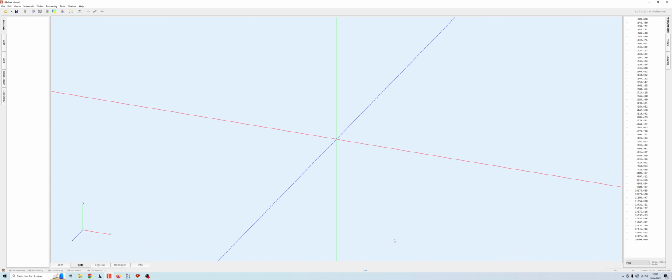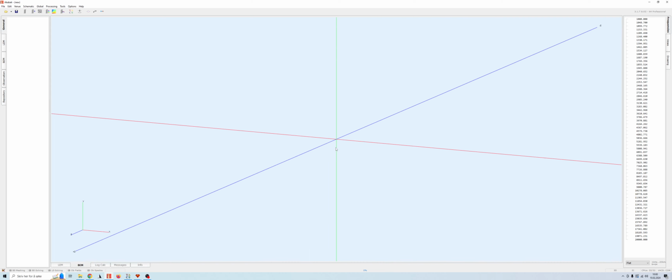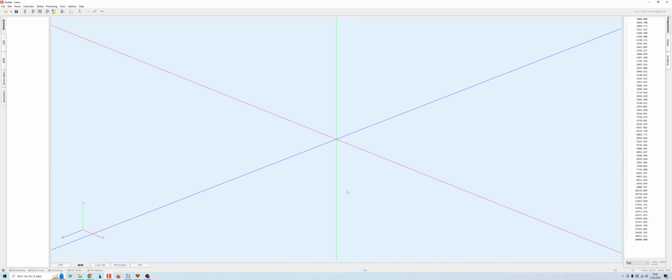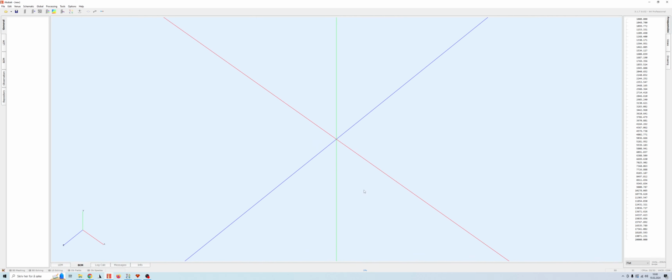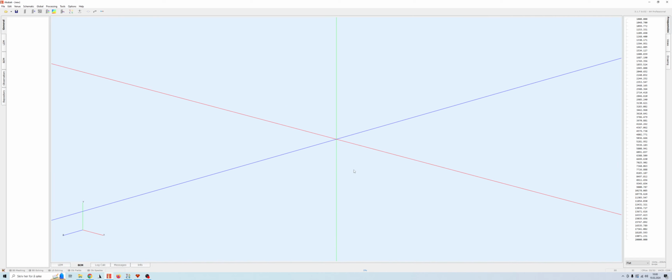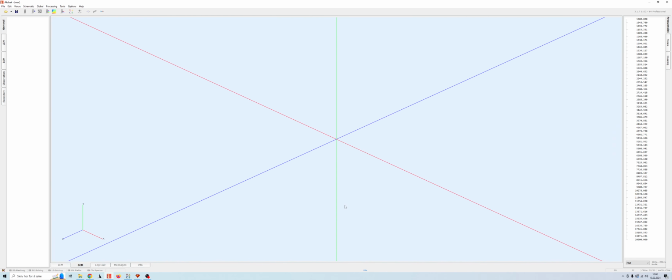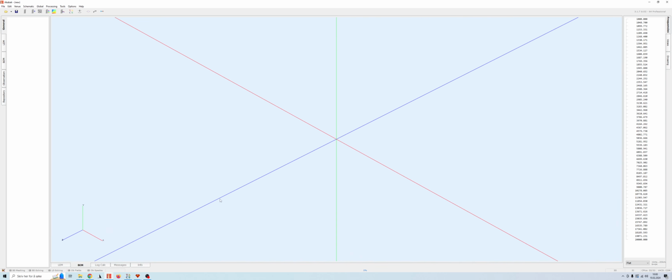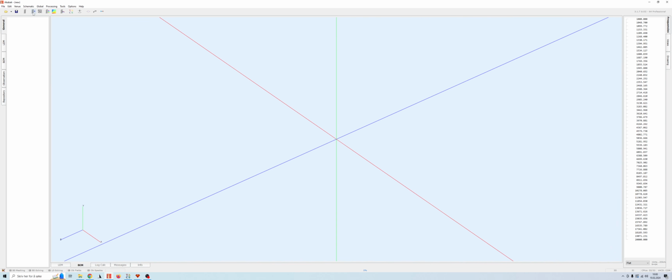In this video, I'm going to be showing you how you can use the circular symmetry mode in AKABAK to simulate a freestanding waveguide. Similar to the 2D simulation mode, the circular symmetry mode is much more computationally efficient than a full 3D simulation. So to start with, we're actually going to go to global and BEM parameters.